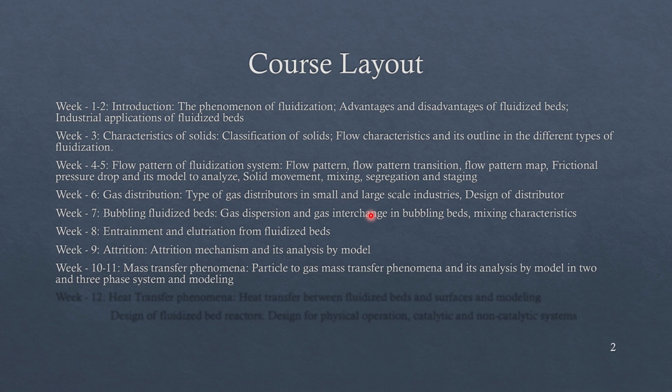necessary to study the mass transfer phenomena happening inside the bed, because we are dealing with so many phases like solid phase, liquid phase or gas phase, and also the bubbling phase. So particle-to-gas mass transfer and its analysis by a model is essential. Thereby we are dealing with two-phase or three-phase systems and their modeling. Different models assume some different properties inside the bed and model them accordingly.